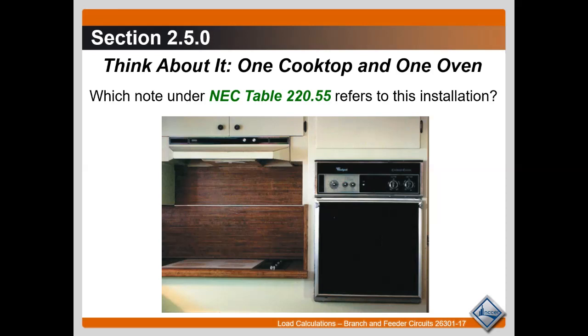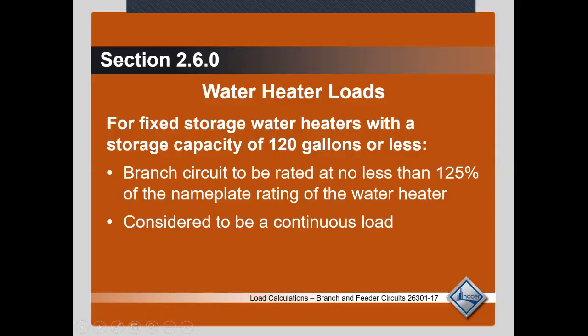Well, for the balance too, definitely to balance the loads. But for that particular reason, anytime you have a computer inside of a piece of equipment, it requires a neutral. That's why a lot of older homes that don't have that 3rd wire in their range or their dryers, their equipment starts giving them problems a lot sooner than newer homes, because they don't have the isolated neutral.